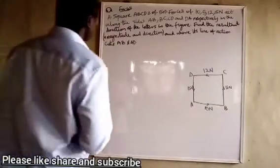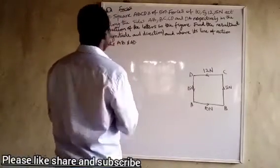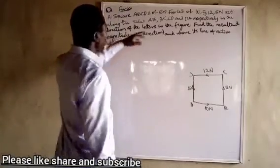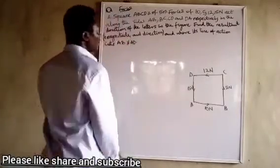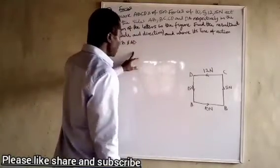A square ABCD is of 5 meters. Forces of 10, 5, 12, 15 Newton act along the sides AB, BC, CD, and DA respectively, in the direction of the letters in the figure. Here, this figure. Find the resultants in magnitude and direction, and where its line of action cuts AB and AD.